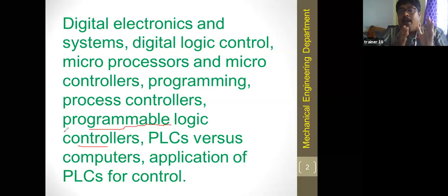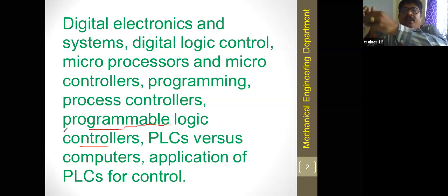Thereby, the single acting cylinder or double acting cylinder will activate. That means the piston will move, with to and fro motion. If it moves forward, we indicate it as A plus, and when it moves back, we consider it A minus. Here A is the name of the cylinder. A plus means cylinder A moves forward, and A minus means the cylinder moves back.